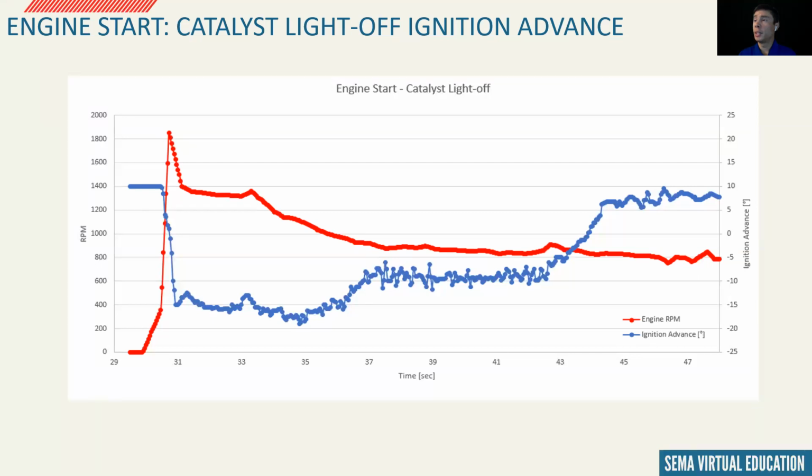This strategy will send the energy or heat out of the exhaust to the catalyst. Catalyst light off will last about 10 to 15 seconds in total, sometimes longer depending on the strategy. This will aid in the catalyst reaching 250 C in about 110 to 130 seconds, sooner the better.